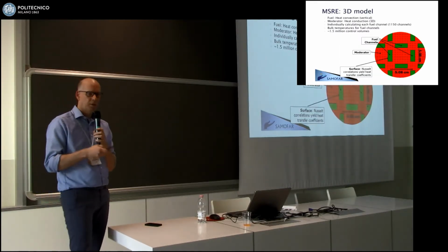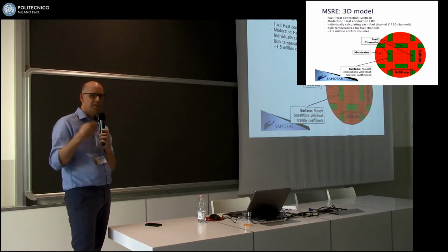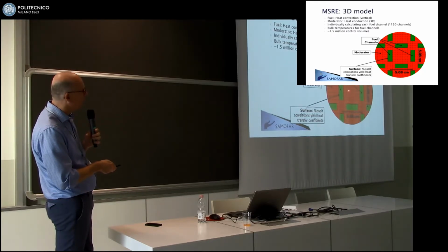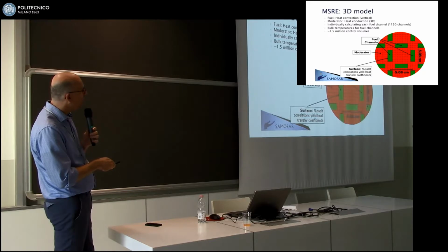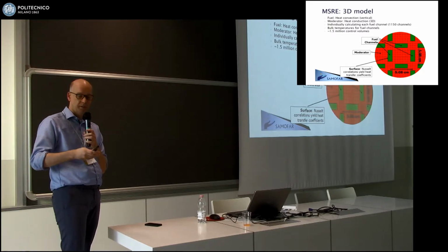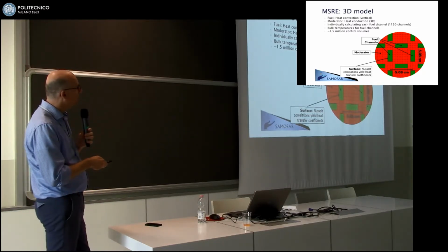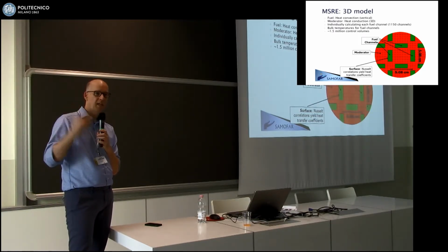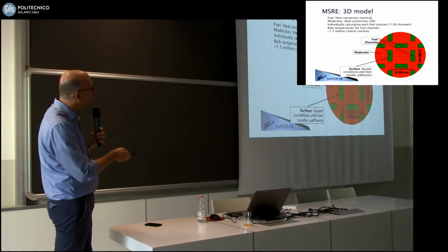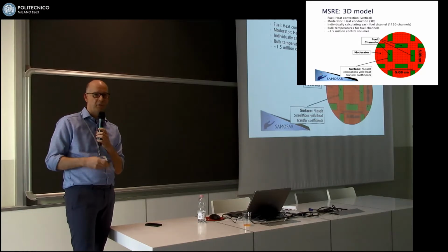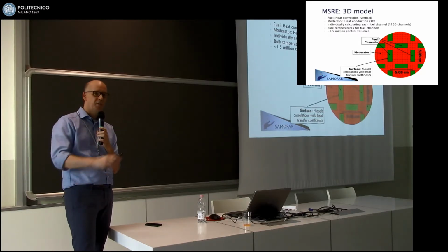A more detailed view of, let's say, the lattice cell. In red, you see all the graphite and this computational mesh that's used for the conduction. And in green, you have the molten salt channels, where we use this one-dimensional flow code, let's say. Each of these channels has been modeled separately. So there are over 1,000 channels. So we use over 1,000 sub-channels separately. And the graphite block has been discretized completely. So that's over 1.5 million cells that essentially couple all of these channels together.